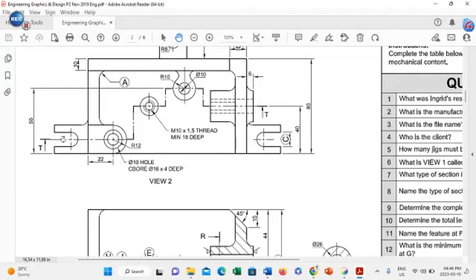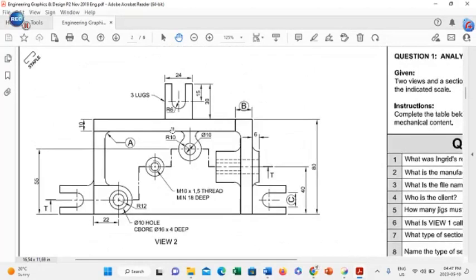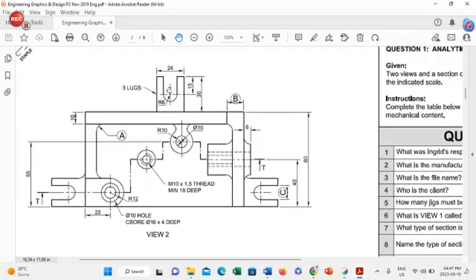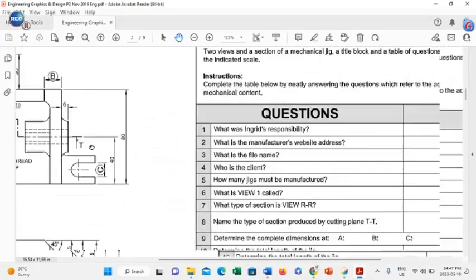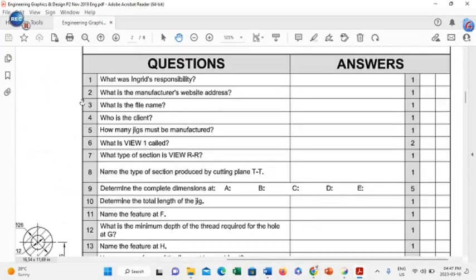There's another one on the opposite side. No information has been given there, but if you scan, you will find that the same slot appears here from the top view. The dimensions have been given here, so the distance in between here is going to be double the R6, because R is the radius from the center to the outside, and double that is R6 times 2, which gives you a diameter of 12 in the space of C.